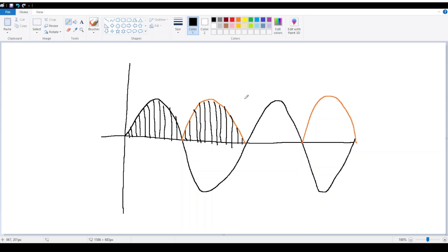The major advantage, as you can imagine, is that we're going to get to the set point much quicker, by the mere fact that we're comparing at every single point. Previously, we were waiting for every 10 milliseconds, checking at that point and then at the next, which is simpler, but it does take time to get to the set point. So this is the general idea of what we're going to be doing.